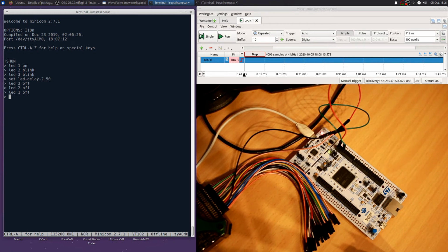There's a UART driver, there's a terminal abstraction that allows you to have some kind of line editing like this. And then there's a command shell that you can extend by writing modules for. So this application has two command shells built into it, this LED blinky one, and it also has one for doing PWM.